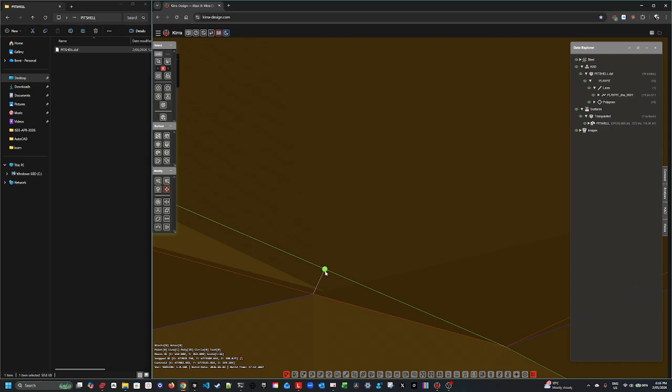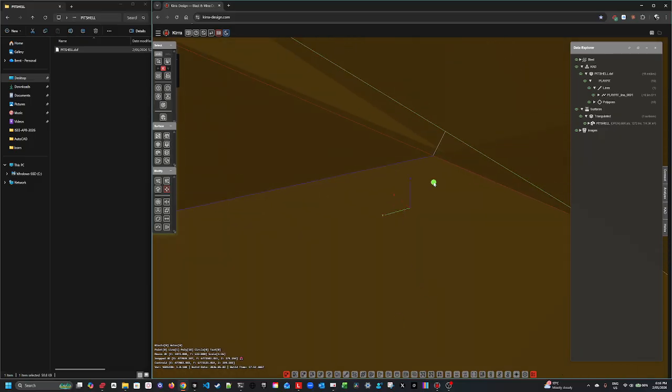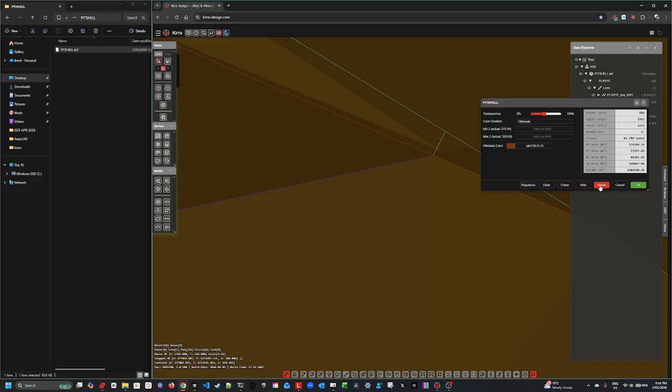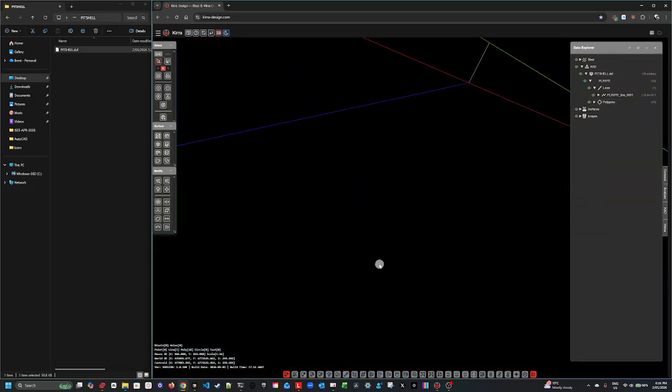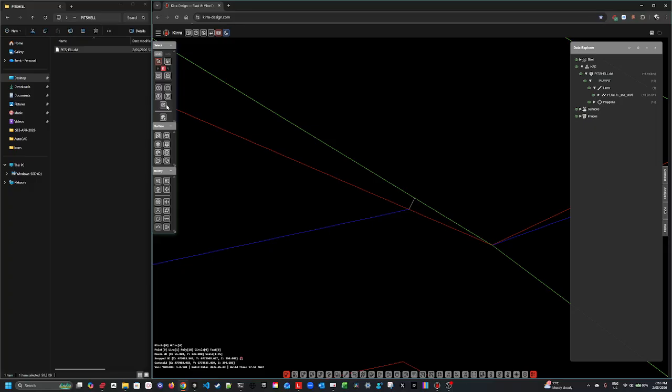Oh, there you go. I don't know why that was playing up, but you can see here I've changed that break line to force it to connect to this area here. So what we might do is we'll re-triangulate our triangulation. So that will mean we'll just delete this one. Okay, let's delete that. And so now we have this break line.